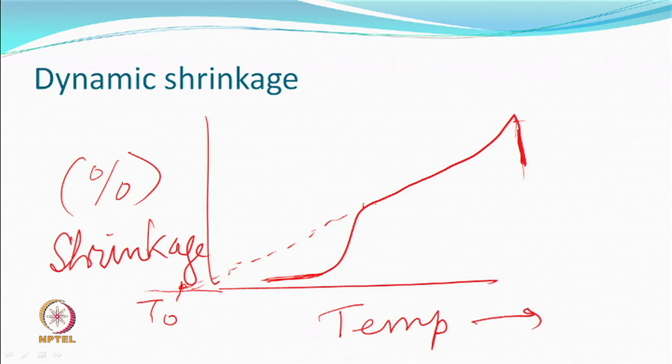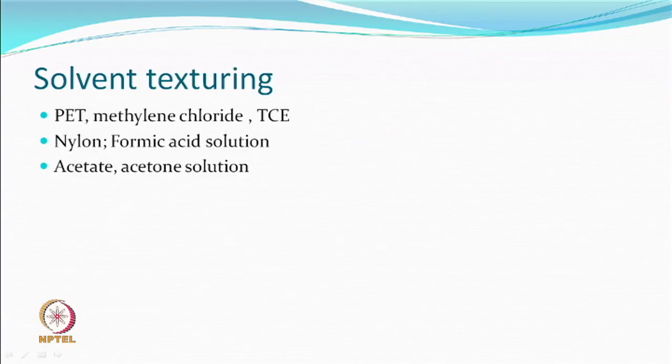You just put a filament in a solvent where you can change the conditions, draw this curve, and then you suddenly get another parameter which is quite indicative whether it is going to be interacting higher, less, and at what temperature you should use to get effective, let us say, texturing, which means decrystallization, recrystallization, everything else. So, some people did solvent texturing. How?